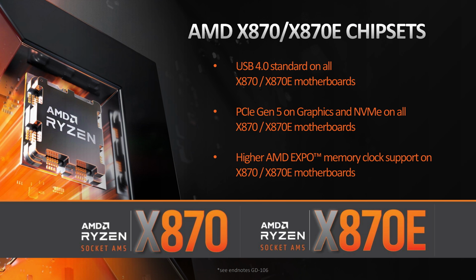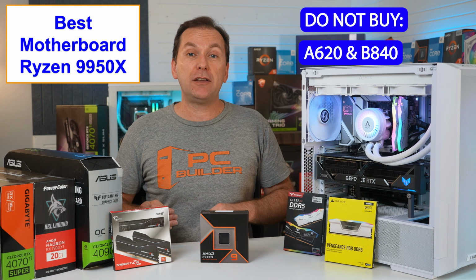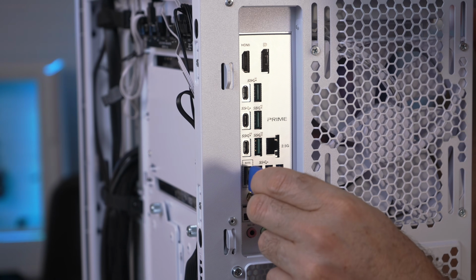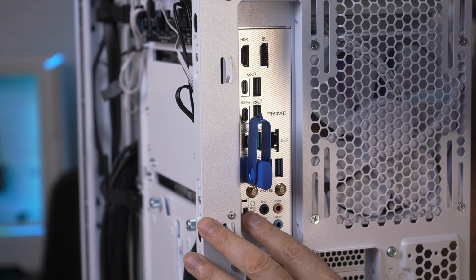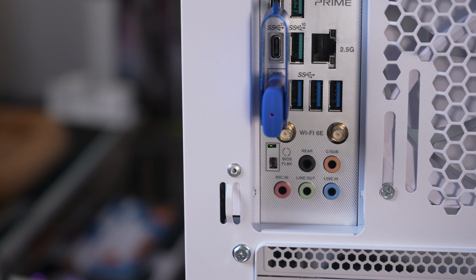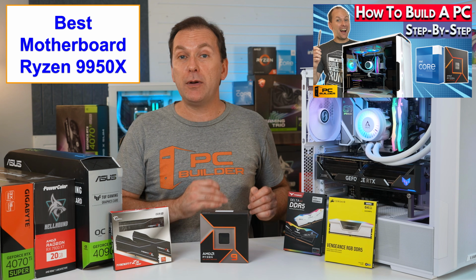Note that the X870 chipset promises to have native USB 4 support, so if that's important for your storage environment, consider waiting for their release. And avoid the garbage A and B840 chipsets for the Ryzen 9950X. We will need to use the BIOS flashback feature on existing B650 and X670 boards to make them compatible with Ryzen 9000 series CPUs. It's easy to do, I did it in this build, and we do a step-by-step in our How to Build a PC video.